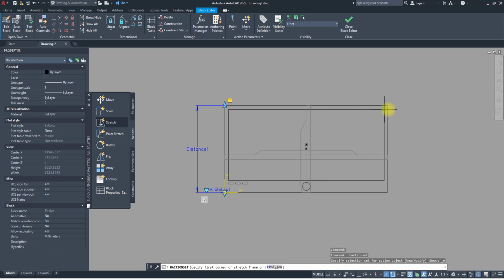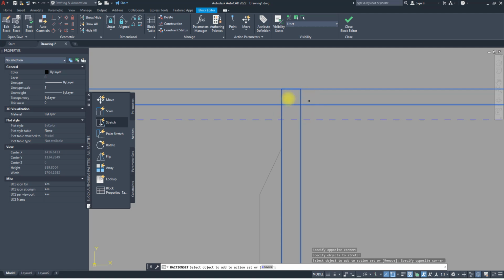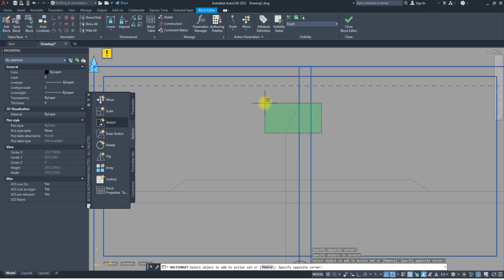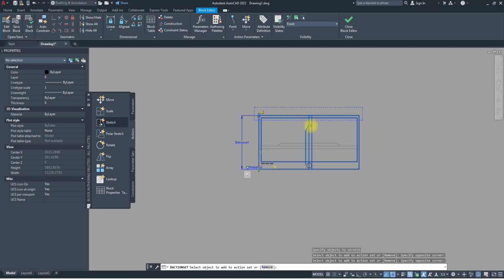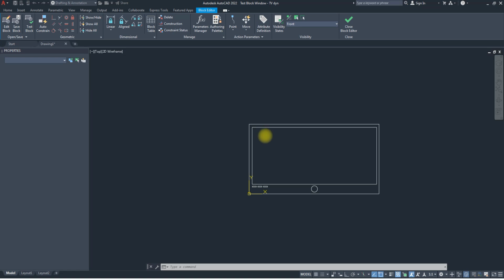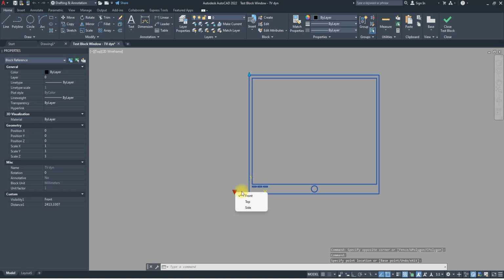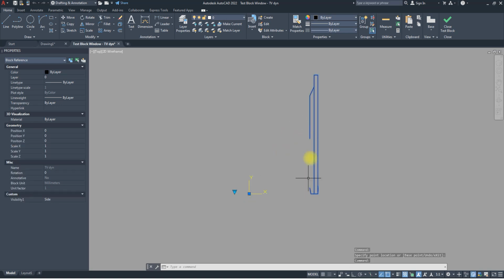Which is why when doing your stretch, if I modify this set, you have to also include this. So go back, select this frame, and then select this object. Notice that object is now added. We don't want this back thing to stretch. Yes, okay. So we have that, press enter. So let's test. If we come here, we can stretch from this view and even go to the next view. It goes.